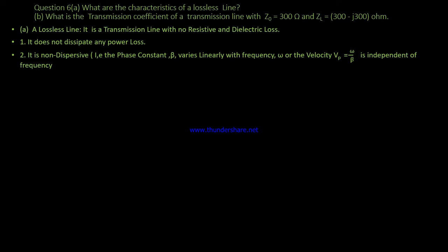Number 2, it is non-dispersive, where the phase constant varies linearly with frequency. Number 3, its characteristic impedance, which is Z0, is real.